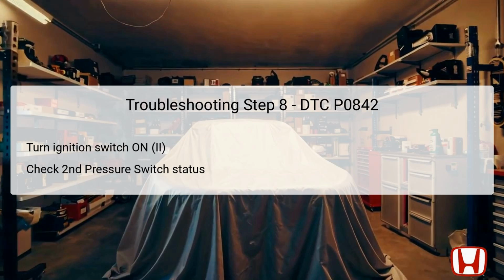If the switch status reads off, it indicates that the component is functioning correctly while not in operation. An off reading suggests that the problem likely lies elsewhere in the wiring or PCM. Conversely, if the switch shows on, it signifies that a fault persists within the component that must be addressed to